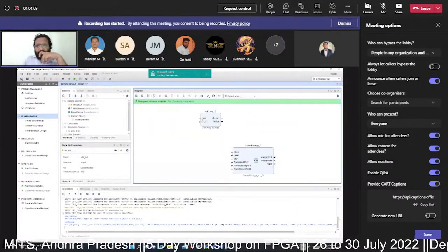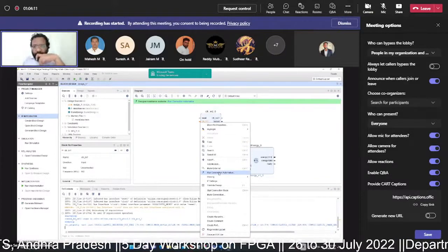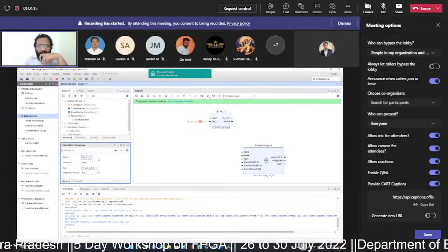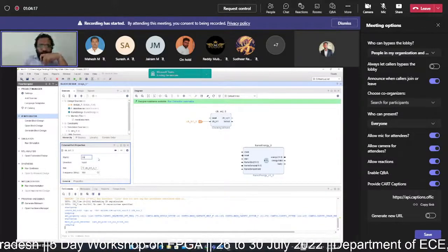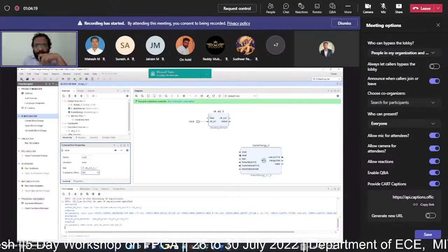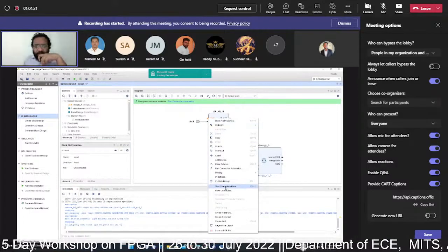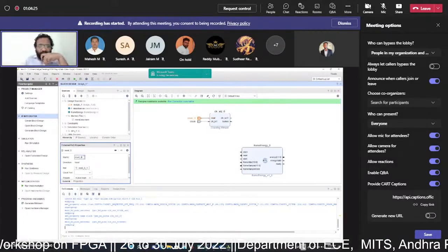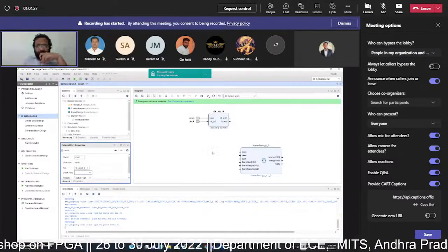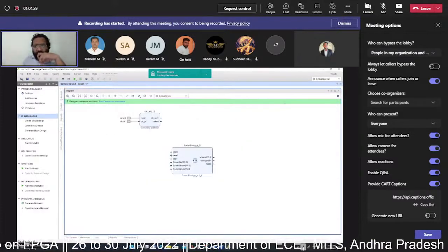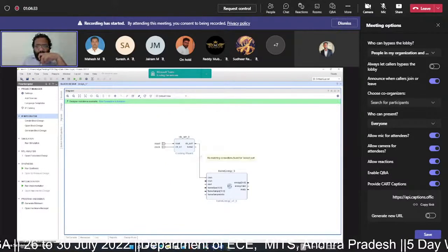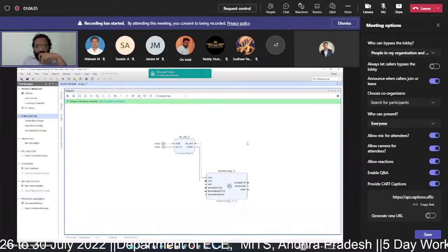Now the clk_in1 port, I will make it external and rename it as clock. Next, similarly, the reset signal I will make it external and rename it as reset. And this clk_out1 I just connected to clock. The locked output I connected to active low reset.